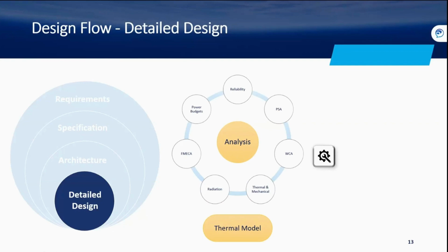Also, we perform the failure mode analysis, which basically consists of verifying that possible failures won't propagate outside the PPU to the rest of the system, and that we don't provoke overconsumptions. Also, we develop finite element models in order to provide analysis about radiation, thermal, and mechanical studies.